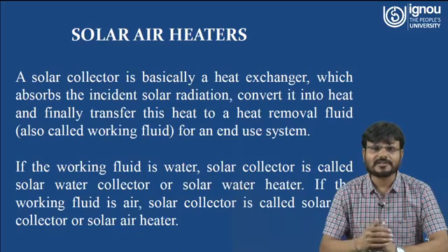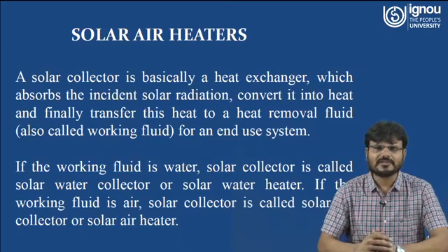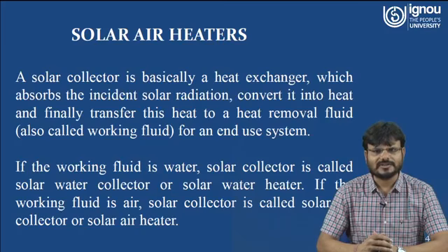In a solar air heater, a solar collector is basically a heat exchanger which absorbs the incident solar radiation, converts it into heat, and finally transfers this heat to a heat removal fluid, which is also called the working fluid, for an end use system. If the working fluid is water, the solar collector is called a solar water collector or solar water heater. If the working fluid is air, then the solar collector will be called a solar air collector, or you can say solar air heater.